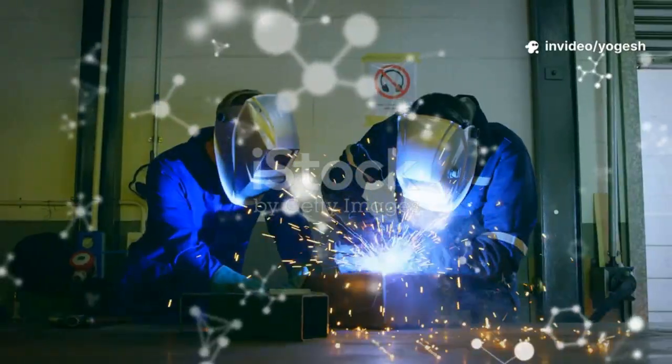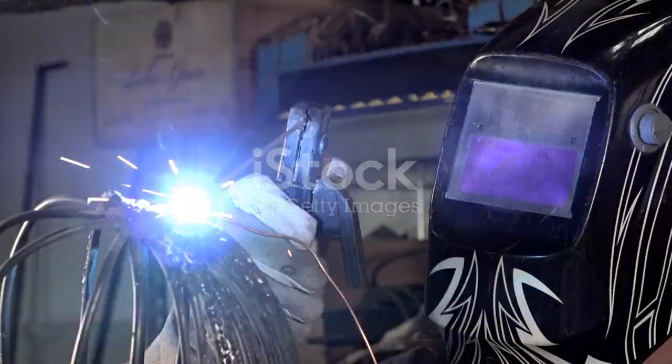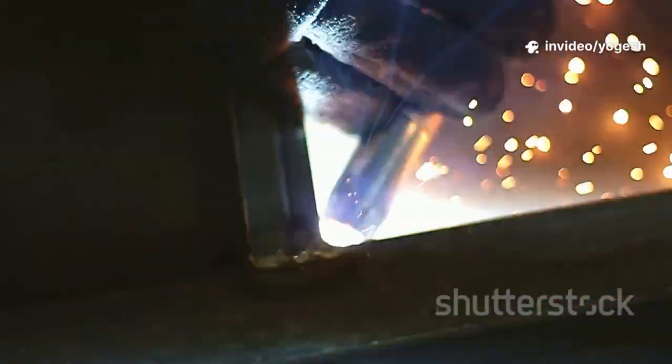Now, let's fill the framework with common weld symbols. The fillet weld, shown as a right triangle, is placed below or above the reference line to indicate the arrow or other side. Size is written to the left of the triangle, making specification quick and clear.